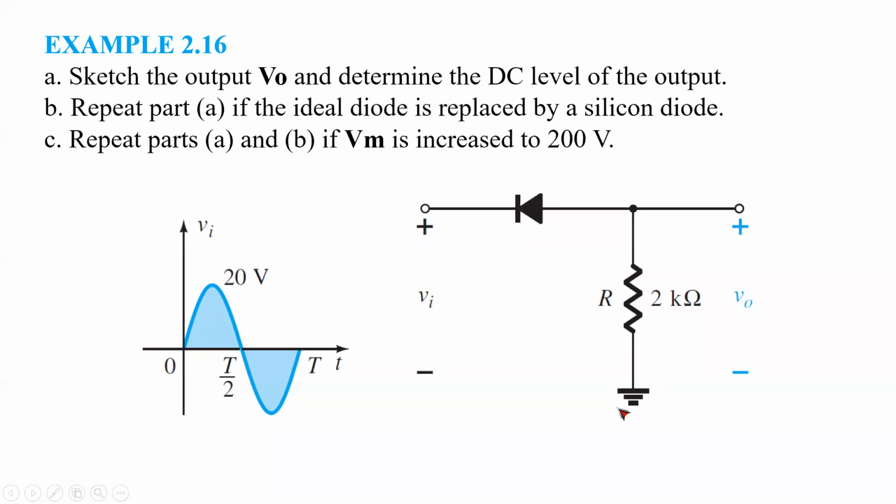There will be no output. Okay? There will be no rectification. Remember, there will be no DC. Understood? Because your diode is damaged. Whenever you put it there, it will be damaged. Your diode can hold 50 volt and you are using 200 volt. That time, instantly your diode is damaged. If your diode is damaged, your rectification is gone. You are no longer getting DC. You are getting AC. Okay? Your rectification, your converter is damaged.